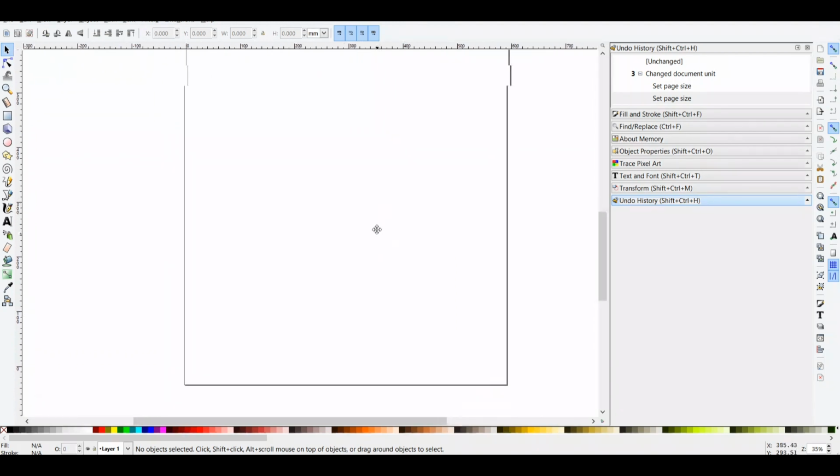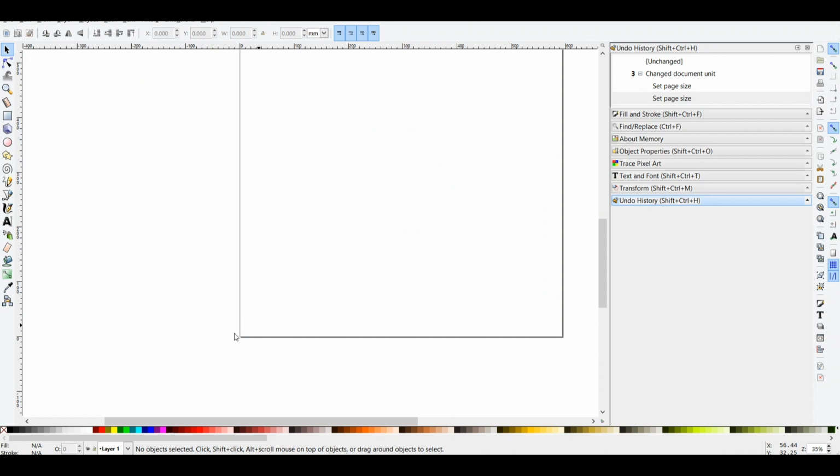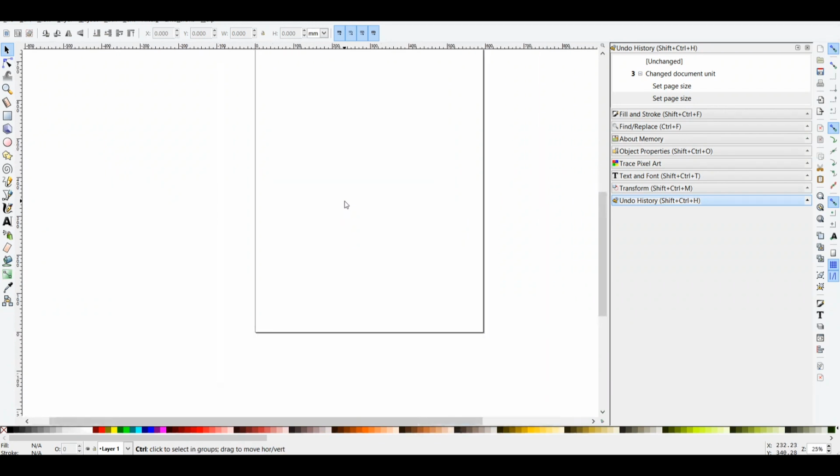You can press on the middle of your mouse scroll wheel to drag your workspace, and the bottom left here is the home position, the same home position as your CNC machine. And then you can hold Control and adjust your mouse scroll wheel to zoom in and zoom out.